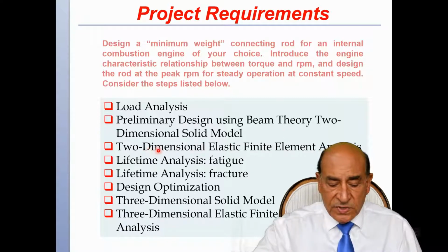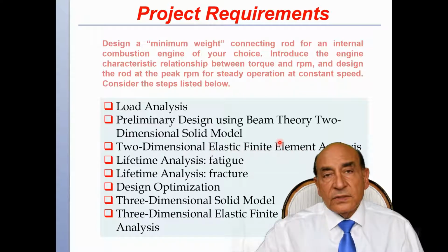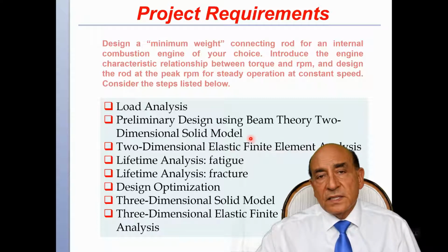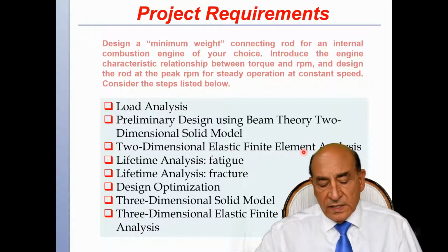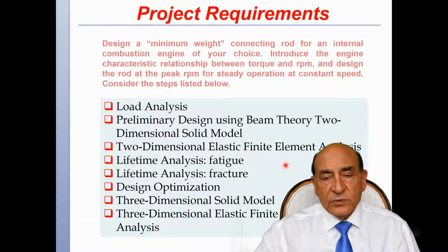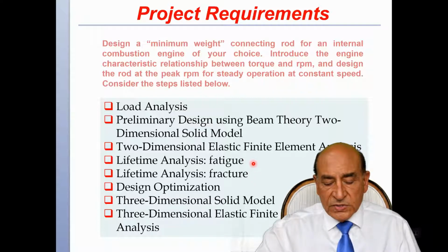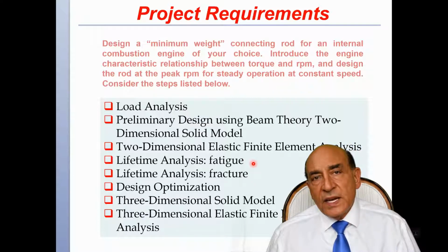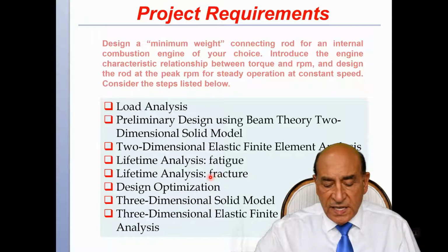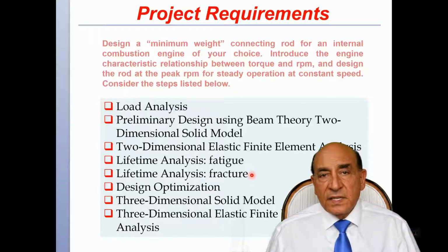And in this case, we're going to do a solid model. A 2D solid model using the elastic finite element method. And then once we have that, we will try to minimize the weight by doing fatigue analysis, fracture analysis, and satisfy the ASME code for design.